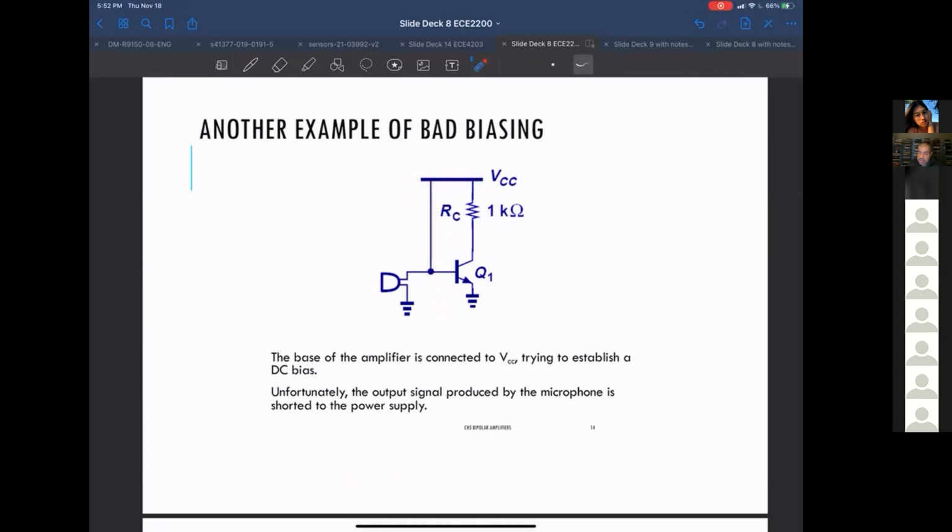So that's also a really bad idea. I don't even know why they bring this up in the book, because it's obviously a very bad idea. All you've done is got this voltage up, so certainly your VBE is a high value. One problem you have, which is not your biggest problem, but it's a pretty big problem, is that depending on your VCC, if this VCC is like 1.8 volts or 2 volts, your VBE is going to be huge.